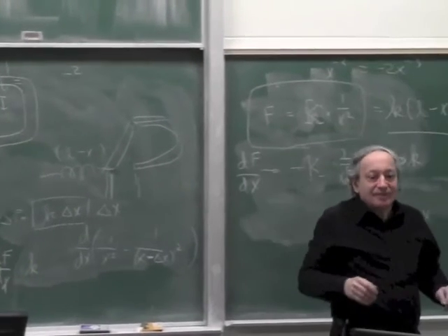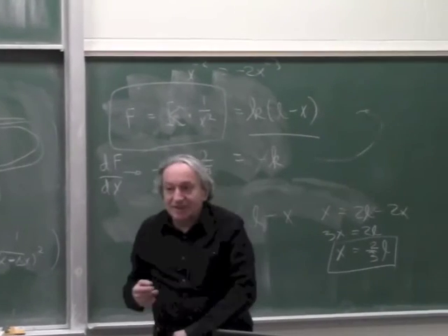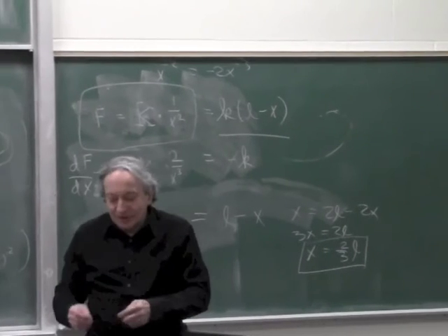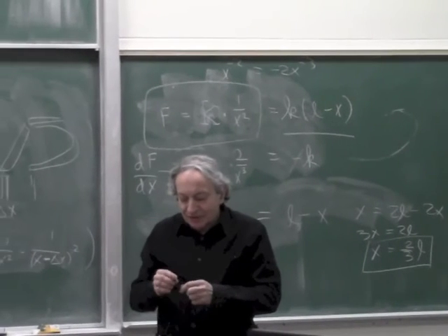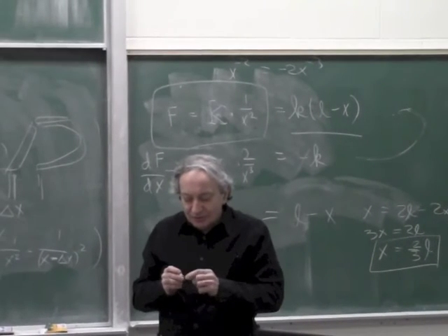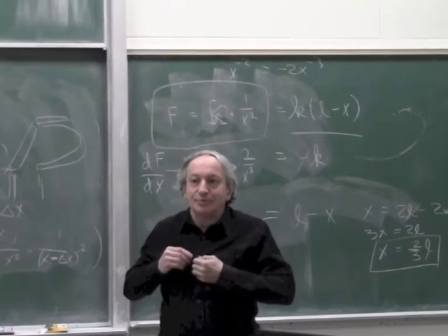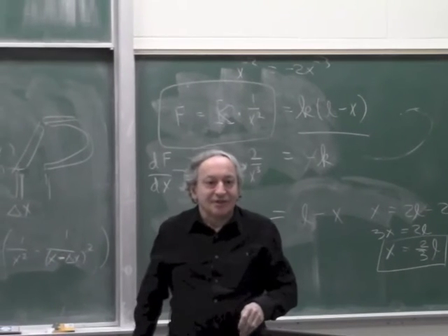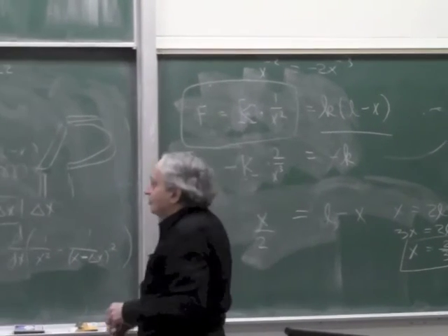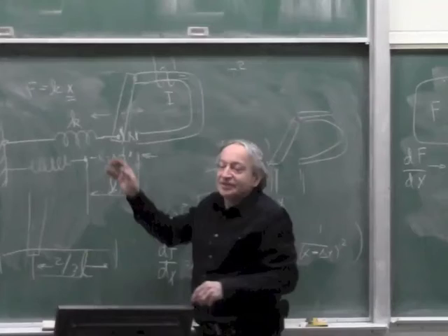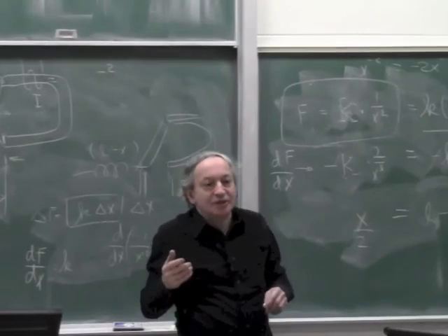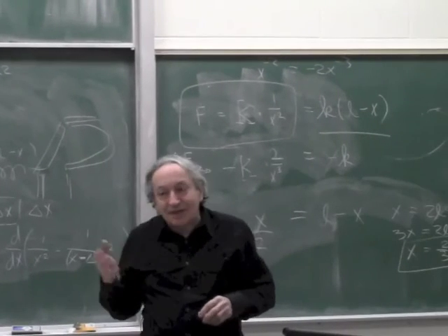Yes? Oh, thank you. So basically that means these actuators are not very good for servo, because you can only use 1/3 of the potential range. And they're also not good, because even in this 1/3, the gain of the servo will change. And we can calculate by how much.